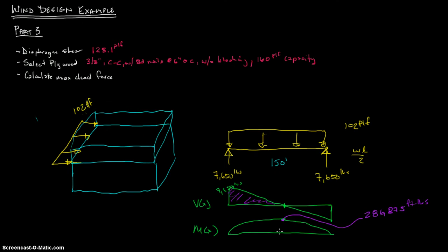So at this point, you want to look at this as a beam, and you want to look at the chord force. What is the reason I went ahead and figured out what this diagram is? The chord force is, the best way I like to look at it is to think of it as a truss. So the chord is right here and right here, and your moment arm is between them. So think of it as a coupling, where you could take the moment about the center line, or you could just take the moment about here, and that means you get rid of this chord. So you're going to have this going this way, that going that way.